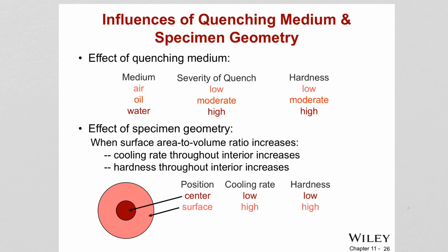There are other factors that affect the quenching. One of them is the quenching medium. Normally you might think we do quenching in water. Actually, there are a lot of other different liquids used for quenching. The quenching medium can have different thermal conductivities, which affects the heat removal from your sample. How quickly it removes the heat will of course change the mechanical structure, and therefore people came up with a variety of quenching media which can create different types of structures in the material.